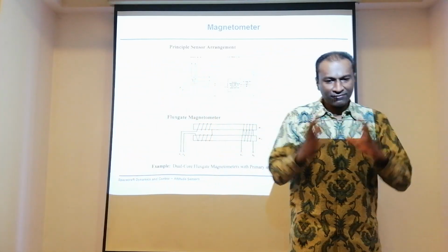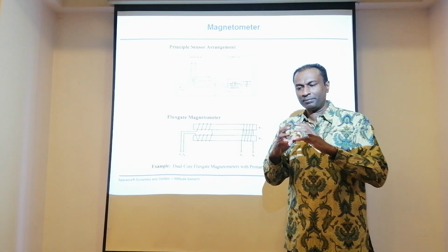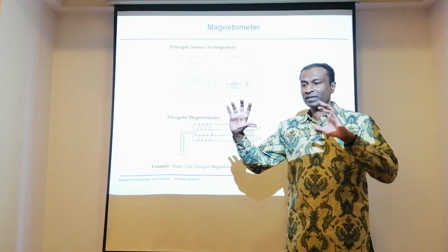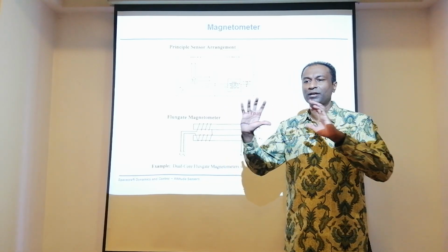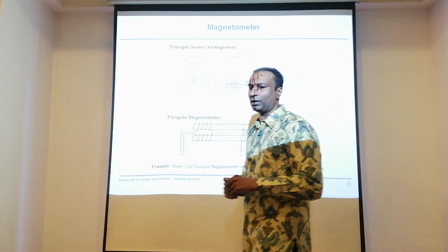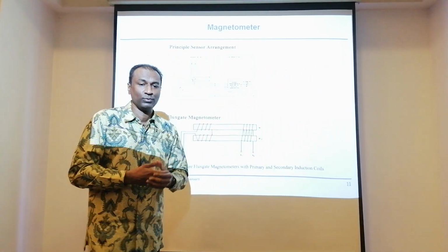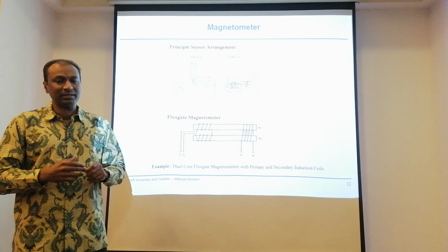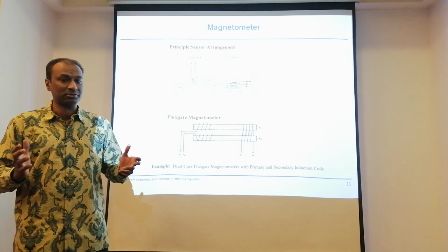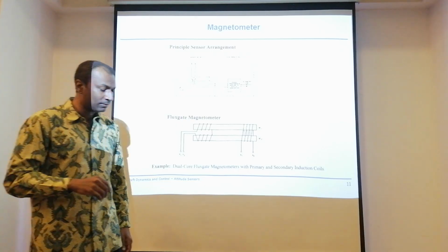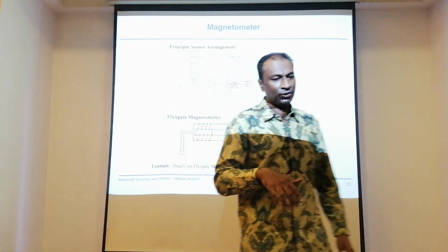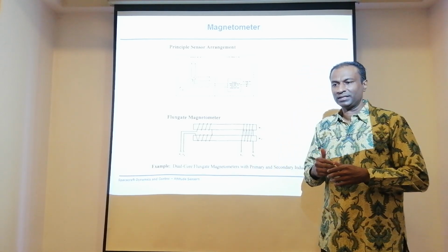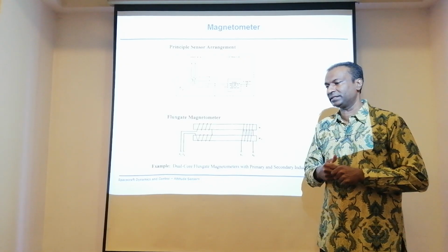Once we have the variation of the magnetic field, we have a complete model, the IGRF model, as I mentioned just now. We can compare, and once you start comparing, then we know exactly what our attitude would be. We should be able to estimate all three axes. But we can't always start estimating all three simultaneously, depending on the orbital motion. But as we have learned before, at least two per cycle is highly accessible.